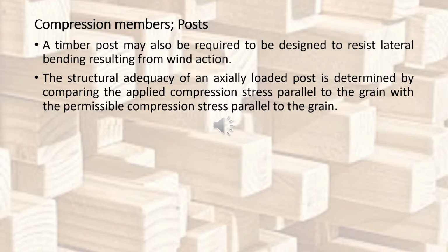So these need to be taken care of in the design of those compression members, right? Many of the structures in timber will have a post being subject to wind action, and you'll have to design the post to resist the lateral bending moment induced.